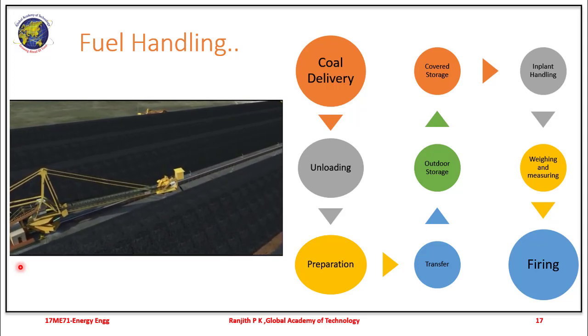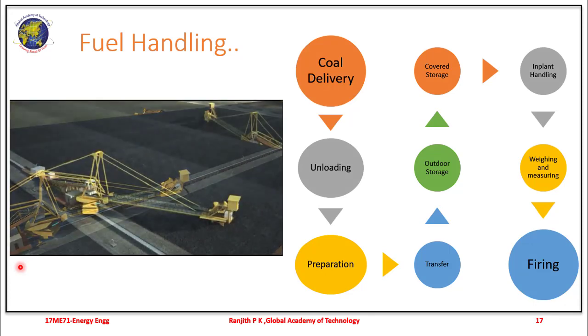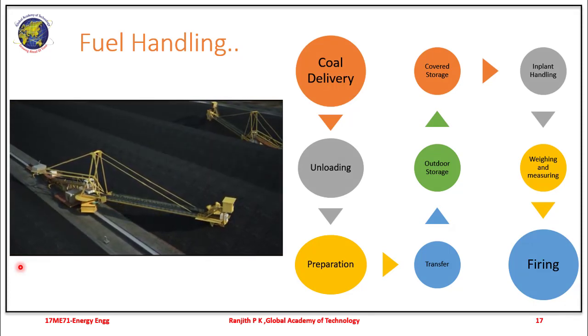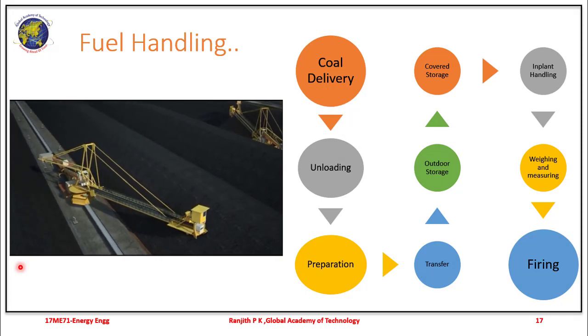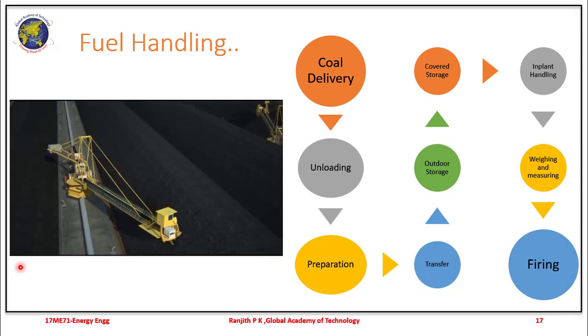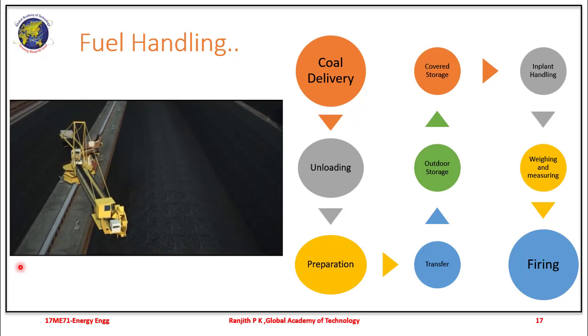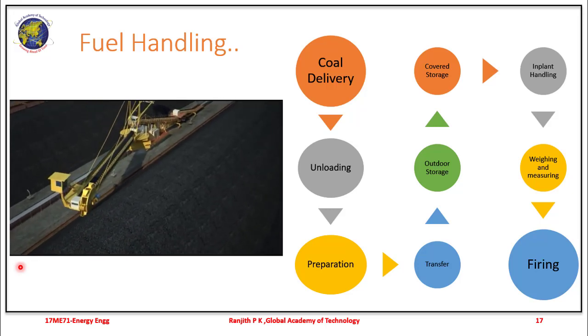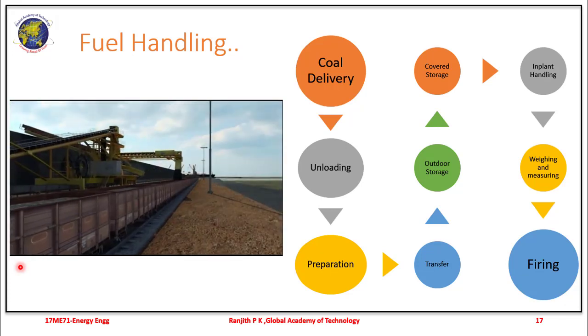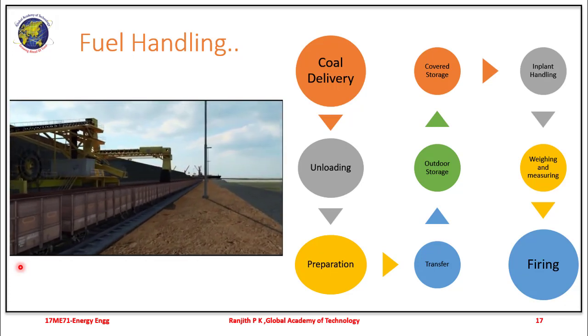The stockyard is equipped with a water dust suppression system at all the transfer points of the belt conveyor system, and water sprinklers fitted at both sides of the coal stockpiles. The stacking operations are basically performed by means of two stacker reclaimer machines. These machines can stack the coal from the berth in trapezoidal cross-section piles, or reclaim the coal from said stacks